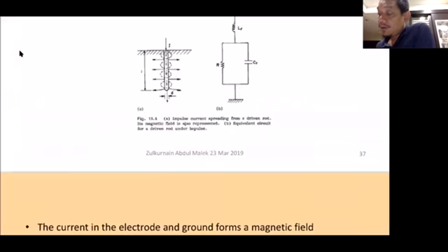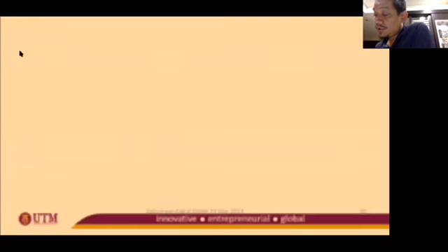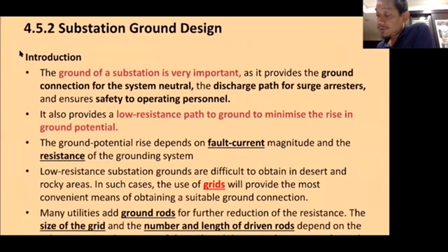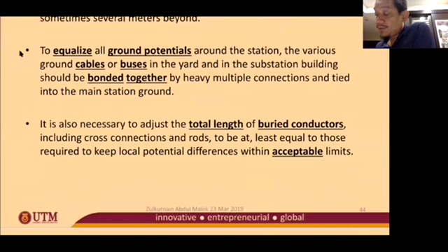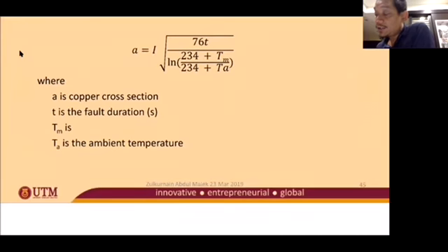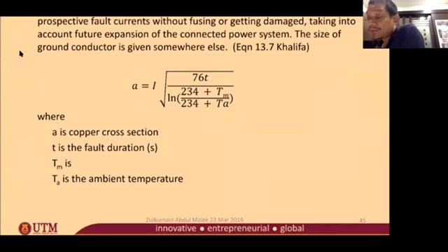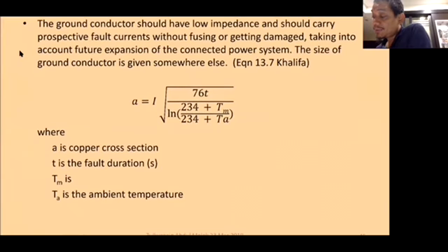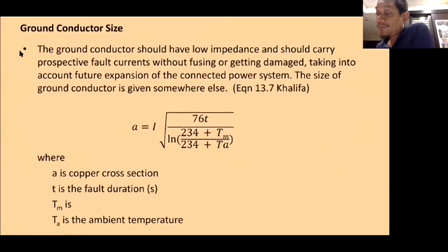Now, you can look in detail at that, whether it's a substation or a tower. So these are the details of the substation design. The touch, this is touch or step. This is the conductor size to give you acceptable, because T there is the time, tolerable time. Maximum temperature rise at ambient temperature, and so on.